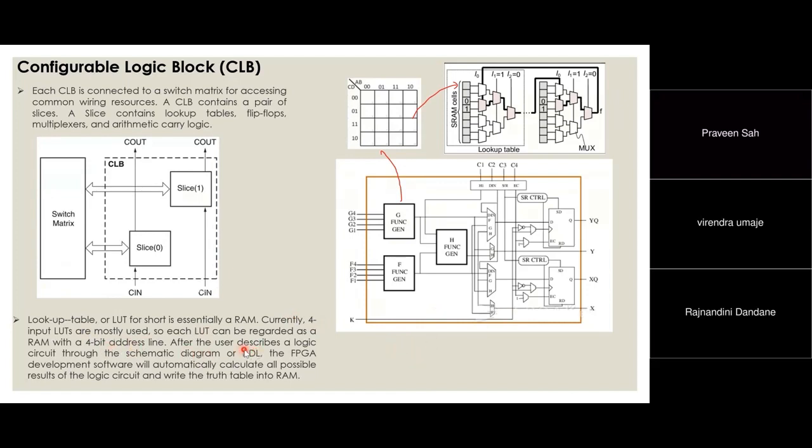Once a user describes a logic circuit, either through a hardware description language or through a schematic diagram, whatever the logic, the FPGA software will automatically calculate all possible results and then write those into this RAM. So this is nothing but the function generator.